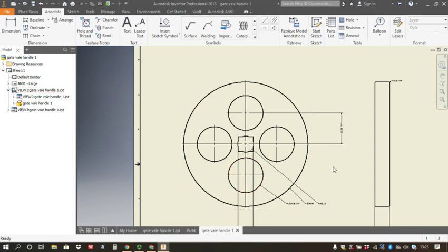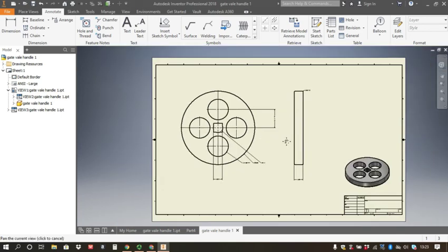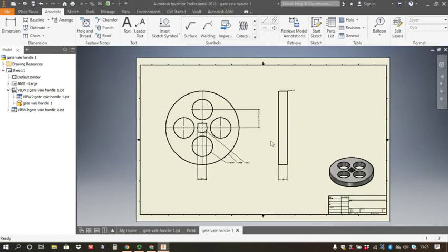Now I could have done this as a PCD, pitch circle diameter. I don't need to do that because this is simpler, okay, and more than acceptable for the course you're doing. All right. Do we now know that every single one of those is in line and 12.5mm? We do indeed. So that is the minimum number of measurements I can get away with for this particular drawing.